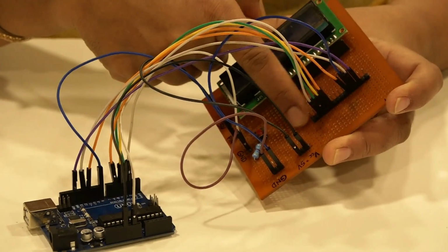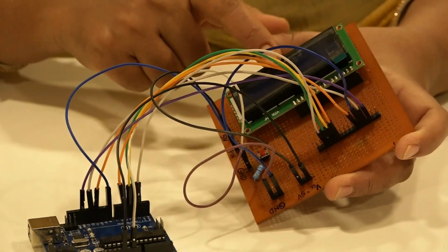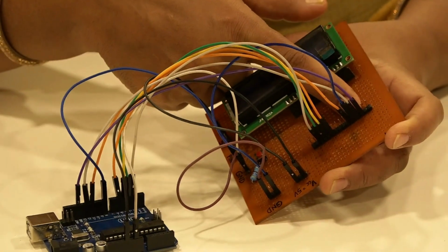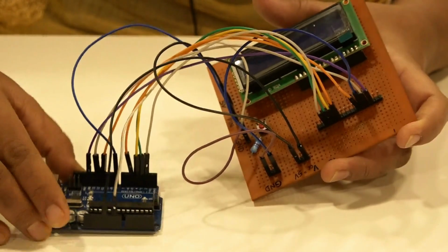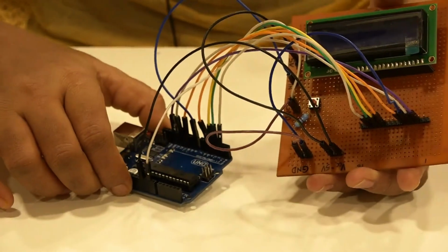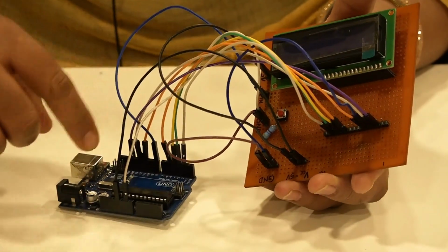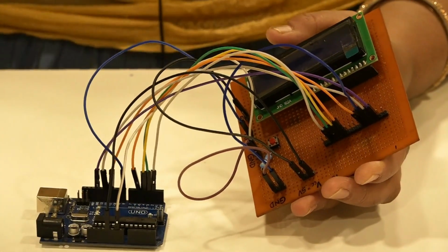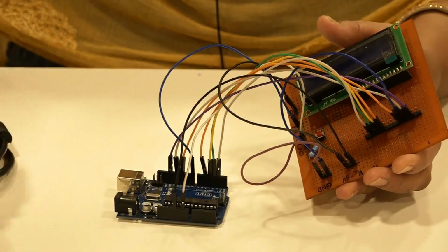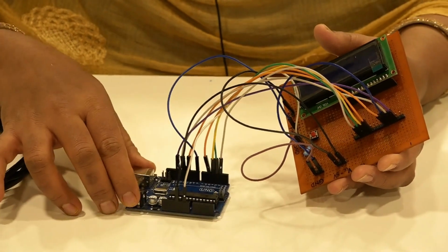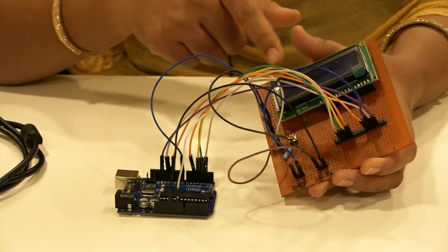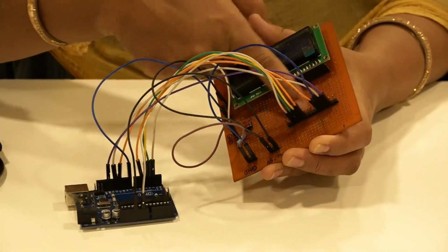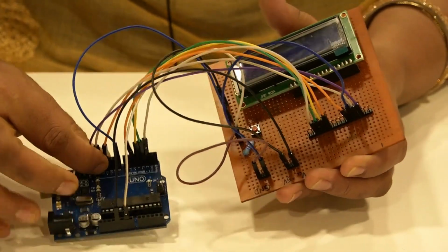Basically, this is the diagram. It is shown in the PPTs, and you have a table explaining which pin connects to which pin. Here it is already connected. After connection you will have a figure like this, and after connecting you can connect the Arduino board to the laptop. Write the program, upload it, compile it, and the output will be seen on the LCD. So, basically you should remember these pins, which one connects to which pin of the Arduino board.